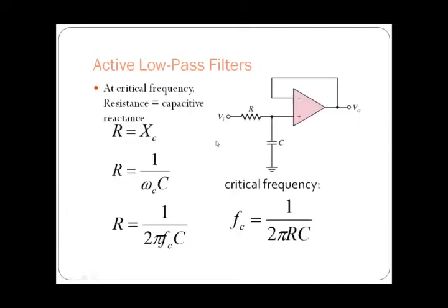And next, we are going to observe the active low pass filter. So see here, low pass filter. Simply, we are going to consider a voltage follower here, and we are giving input here also. We are going to consider the Opamp as a non-inverting amplifier, and the signal is given to the non-inverting terminal of the Opamp through a low pass RC circuit. And as the feedback is directly given, this is going to act as a unity gain follower, in which the output is equal to input.